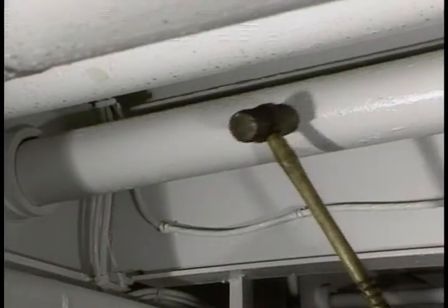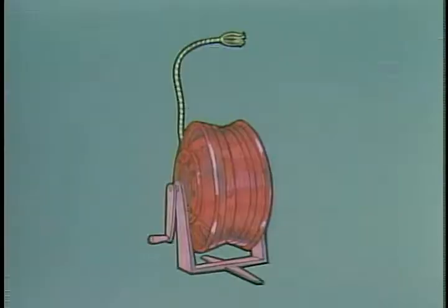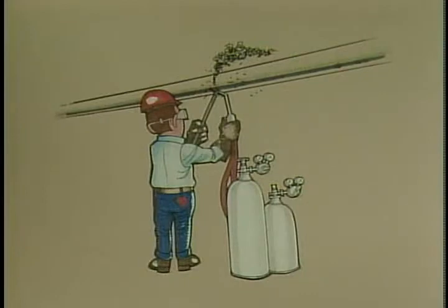If you get a plug, use the old standard methods. If this doesn't work, go get the barge engineer and let him help you. You might be able to use a plumber's snake, or you may have to do something as drastic as cut a section of pipe out to clear it. But that's safer than trying to bulldog it out with air.